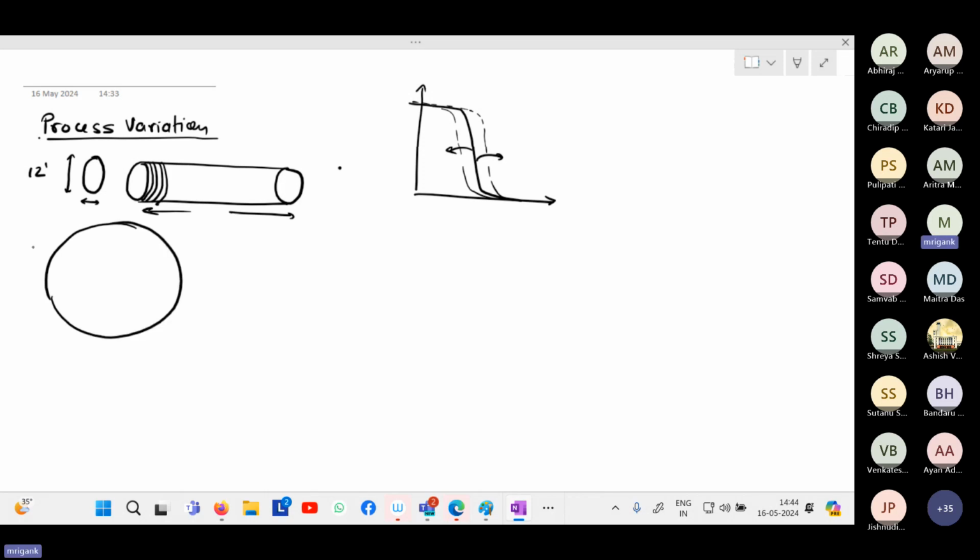And on this thin circular disc, we fabricate the ICs. The way it is fabricated is we print the ICs in this circular disc. We divide this circular disc into multiple segments of, say, given dimension, and the design that you have implemented will be copied into or printed into each of these sections, and then it will be cut out. So this is called dicing.